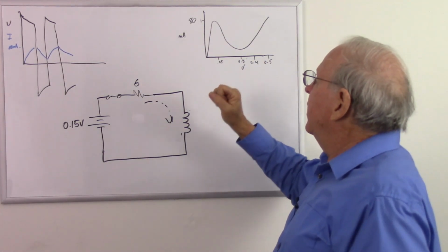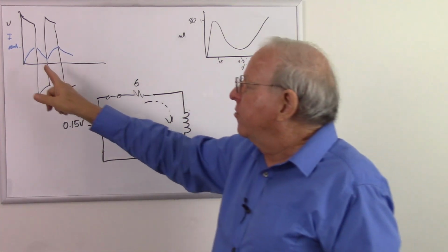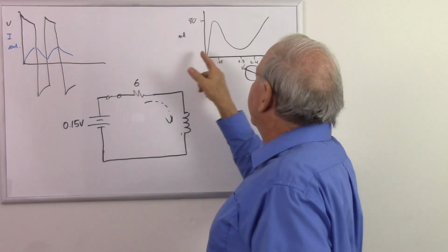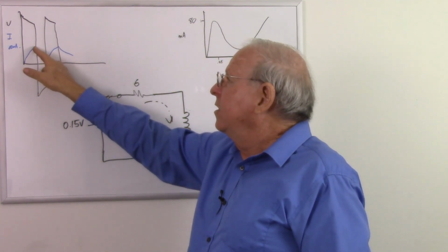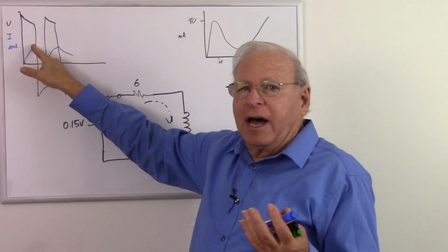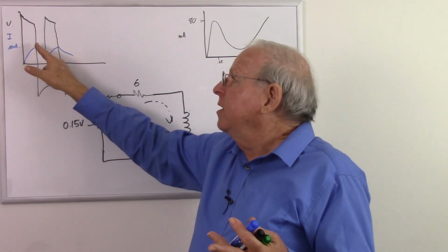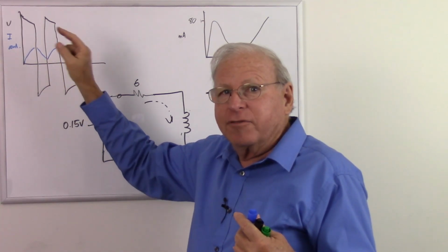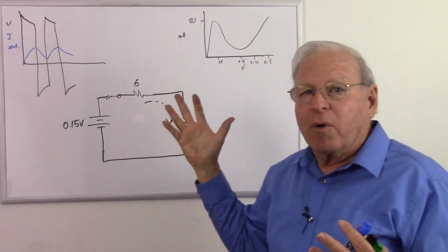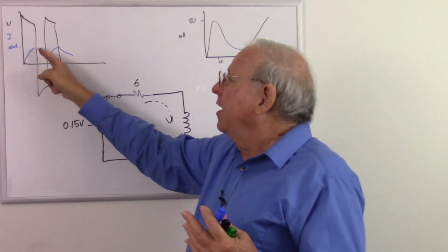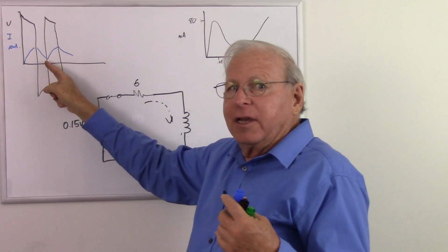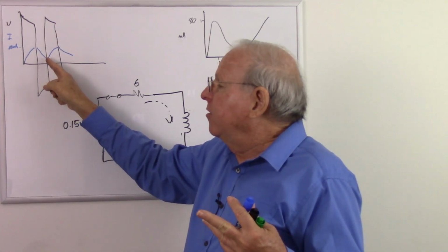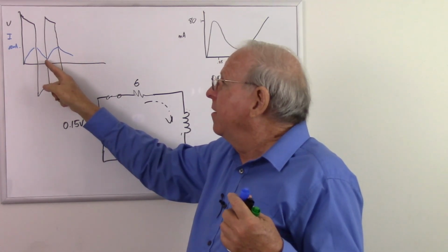And because it changes at different currents, it changes at about 80 milliamps, then it changes at, I don't know, let's just guess about 20 milliamps. So it becomes a high impedance at about 80 milliamps, but it doesn't go back to a low impedance until it gets down to about 40 milliamps. So we have some hysteresis there, which was required for relaxation oscillators. And so it goes back down, and then when it gets down to about maybe 20 milliamps, it suddenly switches back to a low impedance.